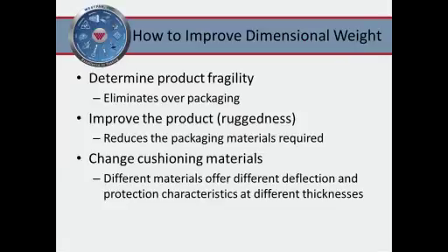And then our common response to that is that, okay, 50 Gs, it fails because what breaks? And they say, oh, nothing breaks. It's just in our specification it says no 50 Gs. And then you ask yourself, because it doesn't break at 50 Gs, but you're still packaging for 50 Gs, what happens? Obviously, you're having an overpacked package, and because of that, your cube isn't as good, because with an overpacked package, you have additional foam, and foam will make your package system a lot less dense than it needs to be.